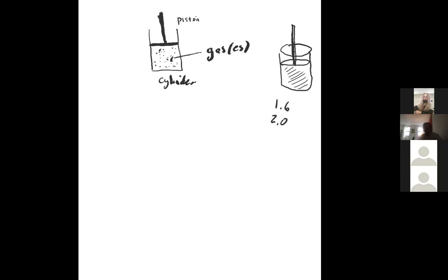So let's say you have 4 cylinders. If you have 4 cylinders and it's 1.6, you divide it by 4. So each one would be 1.6 divided by 4, which is 0.4, okay? Well, that number is liters. It's the size of this cylinder that we're talking about over here. So if you had a 4-cylinder and it was 1.6 liter, that would mean that each one is a fourth of 1.6, so that would be 400 milliliters, 0.4 liters. Okay, so that's really where that number is coming from.